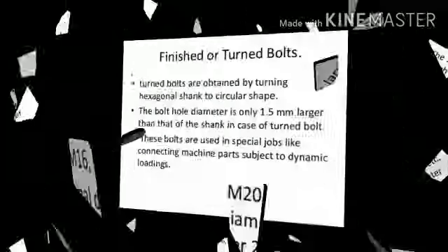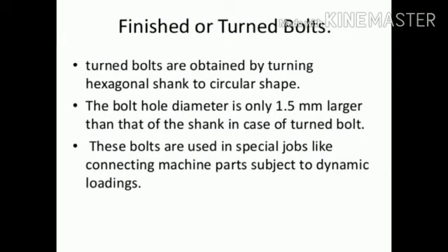The next slide is finished or turned bolts. A screw must be turned to assemble the joints. These bolts are held fixed in place during assembling, either by a tool or by design. These bolts have high shear and bearing resistance compared to the unfinished or black bolts. However, these bolts are obsolete nowadays.